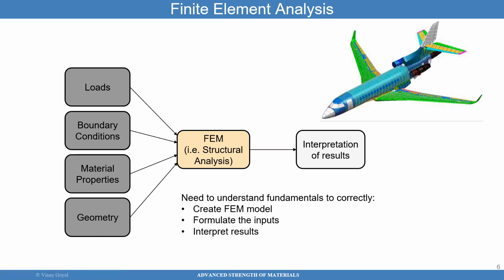So interpreting the results becomes quite important. The other thing you want to do is to then figure out if the rivets could fail, if there are special features that can fail. And typically for those, we use more hand calculations. That's what we want to touch on next, by going through some examples on how that can be done.